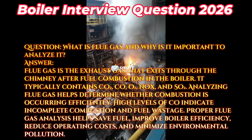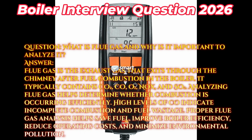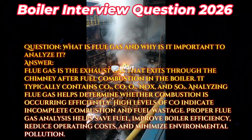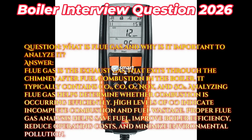Question: what is flue gas and why is it important to analyze it? Answer: flue gas is the exhaust gas that exits through the chimney after fuel combustion in the boiler. Typically contains CO2, CO, O2, NOx, and SO2. Analyzing flue gas helps determine whether combustion is occurring efficiently. High levels of CO indicate incomplete combustion and fuel wastage. Proper flue gas analysis helps save fuel, improve boiler efficiency, reduce operating costs, and minimize environmental pollution.